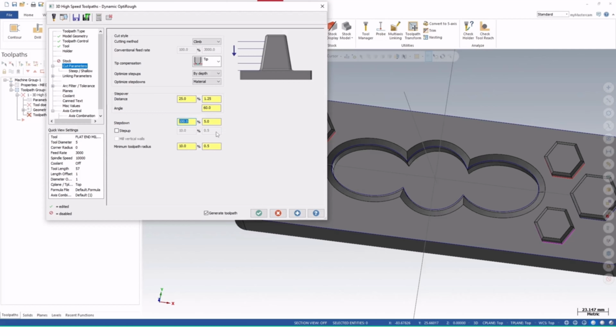If we are using a tungsten carbide cutter, the cutter definitions and parameters will be different. And if you are using a PVD and CVD coated cutter, the cutting parameters will be totally different. So you should know all the cutter parameters and how much the cutter will cut every time.